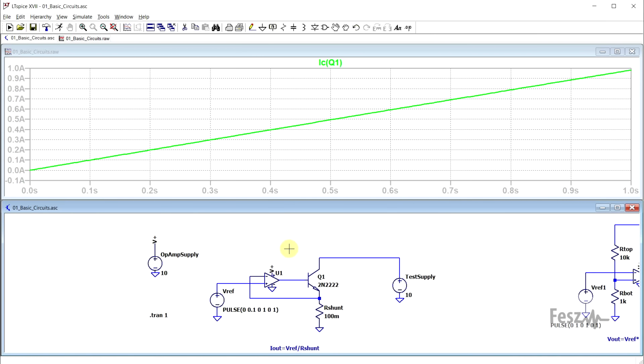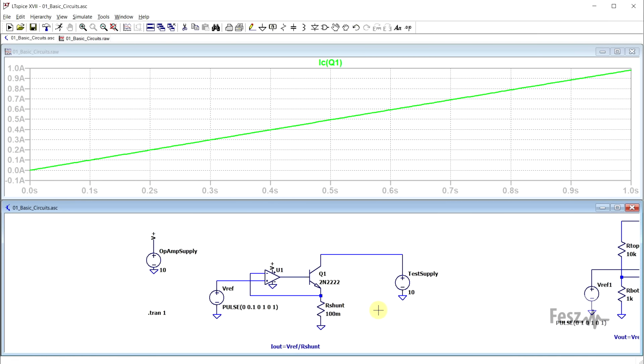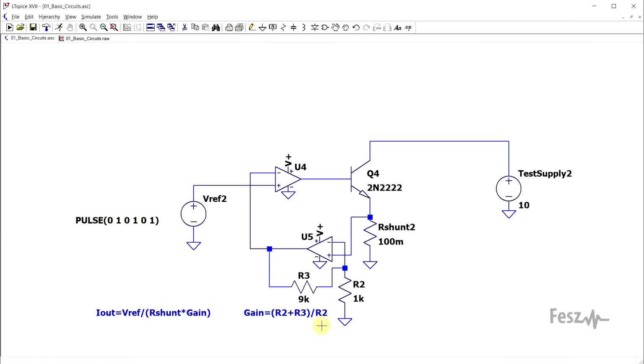Now, before moving on, it's important to notice that while this circuit does work as expected, you need a very small reference voltage and a relatively large shunt resistor. The larger the reference voltage will be, the more voltage needs to drop on the shunt resistor. And usually, you want to minimize this. I mean, to make the circuit more robust, you can either increase the voltage drop on the shunt, which in turn will increase power dissipation, or you will need to use some sort of filtration methods to reduce the noise present in the circuit.